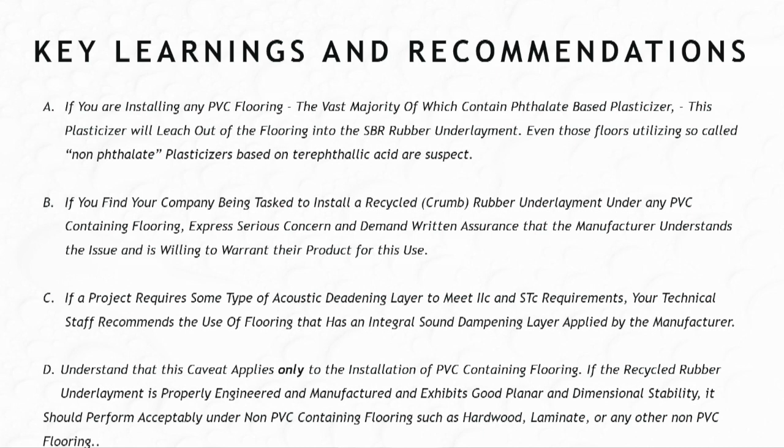Now, George and I and Lou strongly recommend that if you're going to have a project that requires sound deadening, and that's more and more common as we get more hard surface floorings as opposed to soft floorings, you select an LVT or an LVP that has an integral sound deadening layer as part of it. Let the manufacturer of that product be responsible for engineering it, for installing it, and for the compatibility between that layer and the actual vinyl flooring itself. That way it takes the responsibility off you. All you have to do is get it down to the floor, and the rest will be handled by the manufacturer.